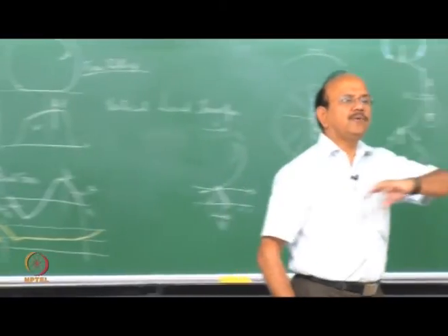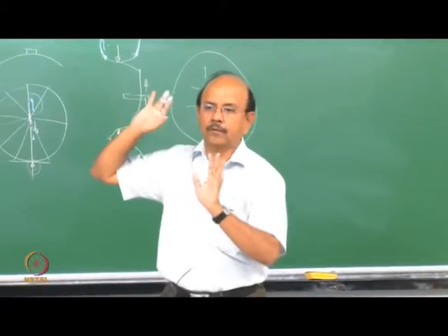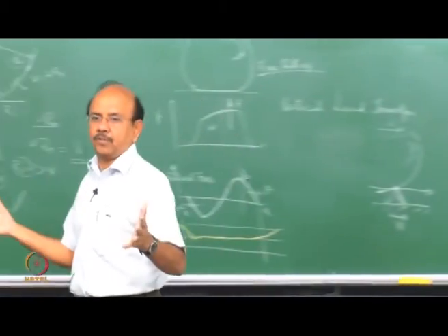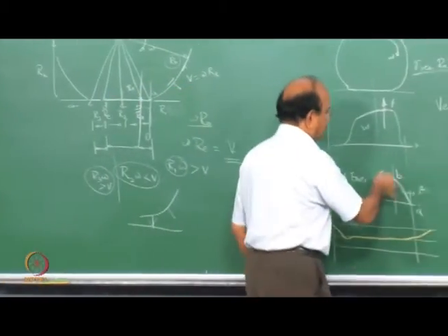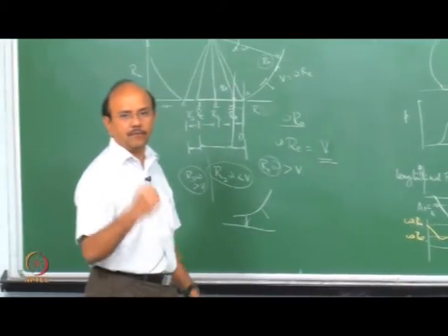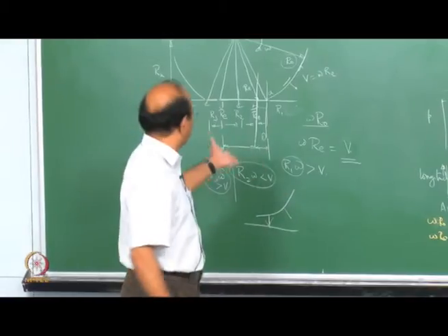So when the tread gets up from the tire and goes out, all those longitudinal forces have to go to 0. Right? That's what happens. All the longitudinal forces go to 0, because it is outside the ground.